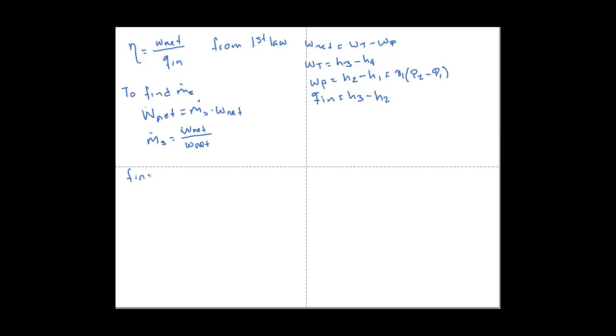Remember that this is different from the 2000 kilograms per second. And finally, what we do in the condenser is an energy balance. We know that this condenser power that we are dissipating is equal to the mass flow rate of steam.